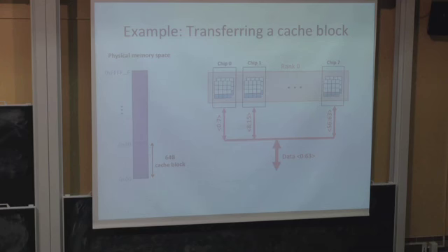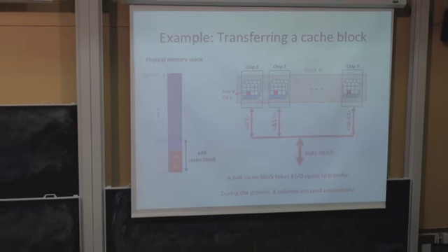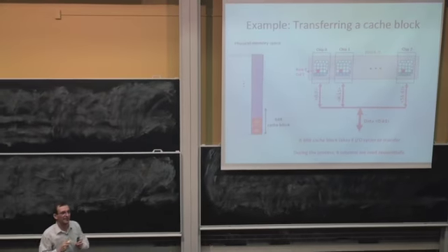The memory controller says, give me the first 64 bits of the 64-byte cache block, and let's say it happens to be mapped to row 0, column 0. So you get the first 8 bytes. And then the memory controller asks for the next 64 bits. You get 8 bytes. And then it asks for the next 64 bits, and you get 8 bytes. Okay? Now, because these are mapped to the same row buffer, DRAM chips are optimized to give you data quickly from the row buffer.